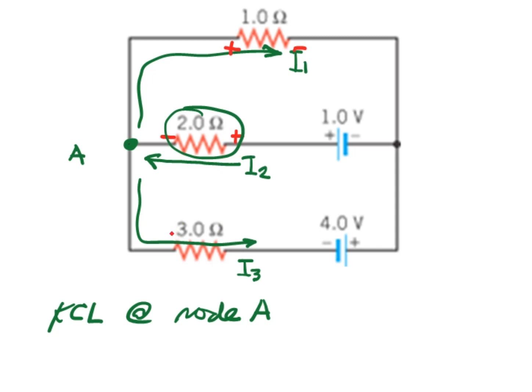And this is also positive, then here is negative. So again, we first assign the direction of the current. You don't have to be afraid to assign whatever direction, because later on, from the answer you get, you will see if the direction of the current you assigned was reversed.